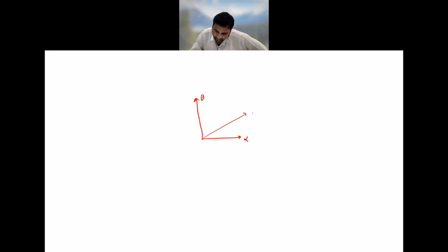Now the next set of vectors we have defined is the dq vector, which is actually rotating in space with the same frequency as that of the Vs phase space vector, which is rotating at omega speed. If you look very carefully here, you can also take the q axis lagging. There is nothing saying you cannot, but once you define the q component in the lagging form, the entire representation of going from alpha to beta, the entire circuit model, will change accordingly.